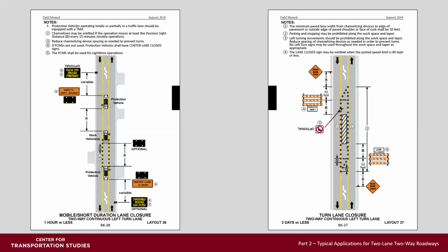Take a look at layout 36. It's for 1 hour or less. Notice that a lot of the traffic control is provided by vehicles. And layout 37 is for the same situation for up to 3 days. Again, restrictions on turning may be needed.